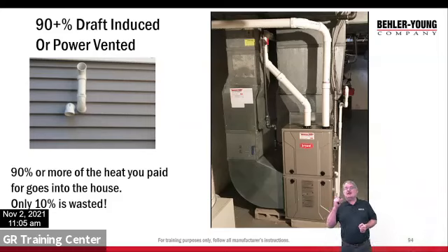All right. So one of the things you'll notice on this furnace is they're using plastic venting material because there's water going to run through it. All right. And it can't be metal. It'll rust, obviously. It'll leak. It has to be watertight. It has to be waterproof.